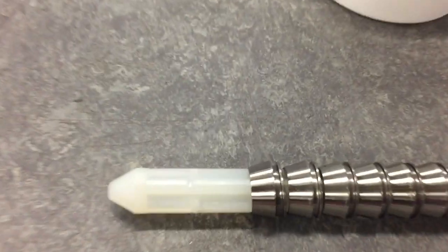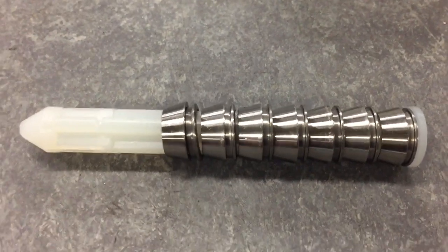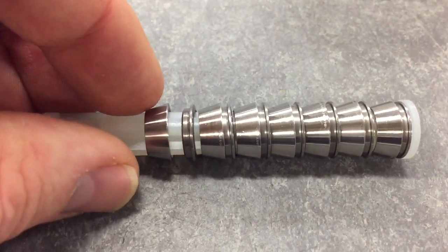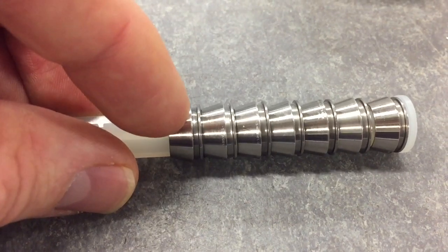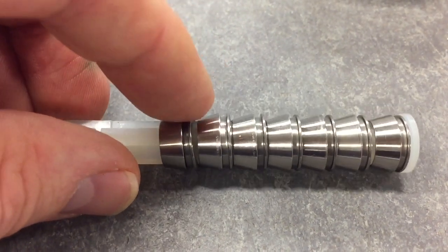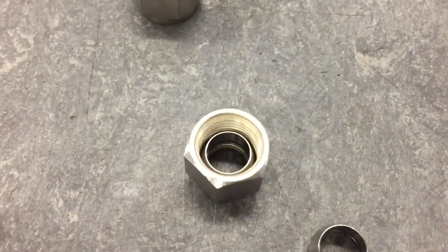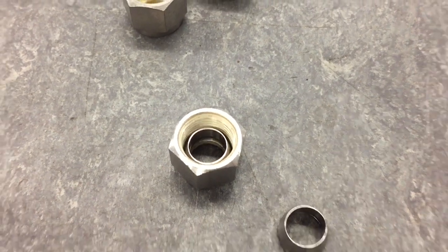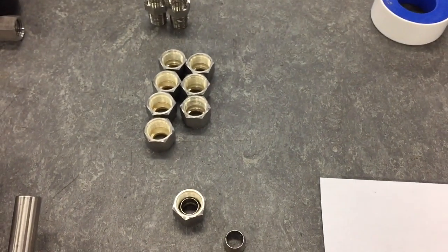And you can see here these are all in that same position right here. You can see that the larger part sits on top just like that. And so when it gets dropped into the fitting, into the nut, sorry, we want to be dropping it down like this. So it looks something like that. So I'm going to go ahead and install all of the ferrules in these remaining nuts.